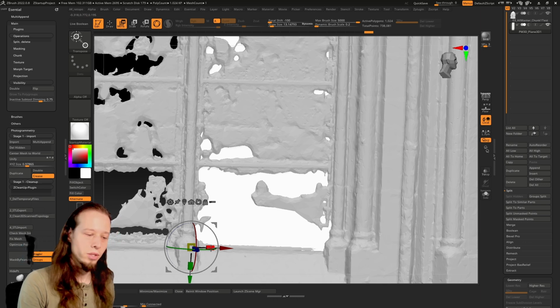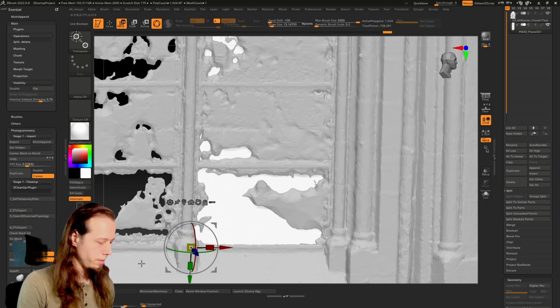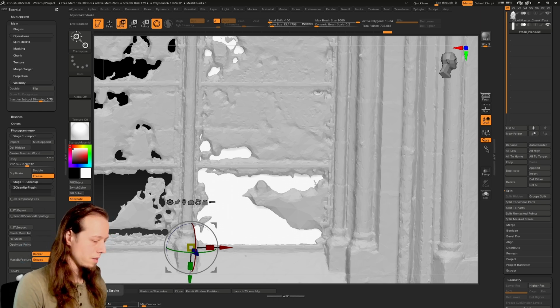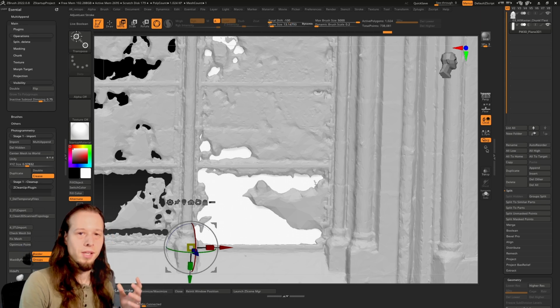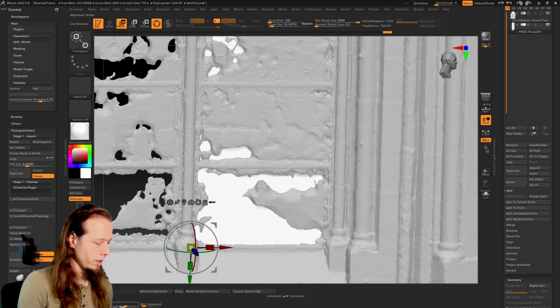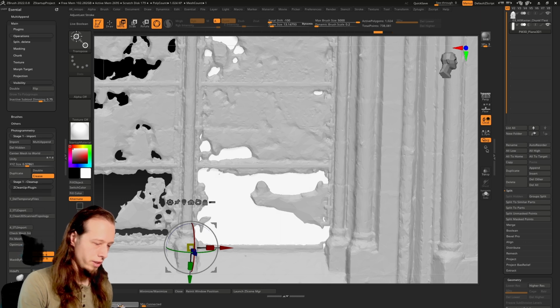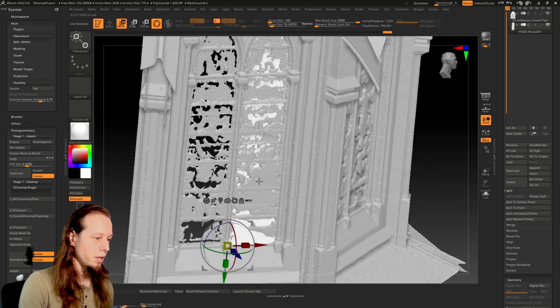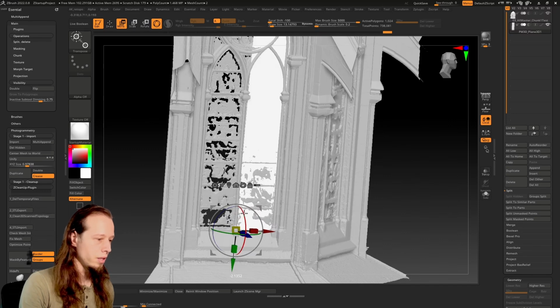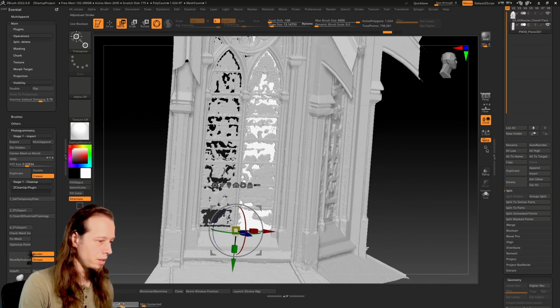And now this additional trick for you, or function of ZBrush, called Adjust Last. We see that under Stroke, and that button takes the last action and the current one and allows us to make a smooth transition between those two. So as you can see, I make a rotation, and now with that I can make the precise adjustment. It's very useful for that kind of situation, because now I can make a rotation of the panel to match the top part and make the adjustment very nice and easy.